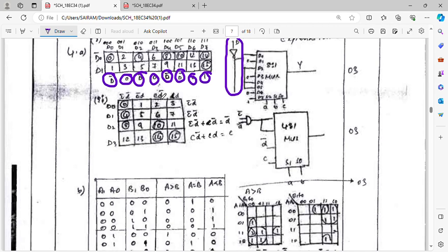And the next thing is you're going to do using what I can say the 4:1 multiplexer. So for the 4:1 multiplexer, take a 4 variable K-map, write the K-map how I have told you to write the K-map in the K-map session. So whichever numbers are present in the question, mark all of them, those are considered to be 1, all others are 0, right?